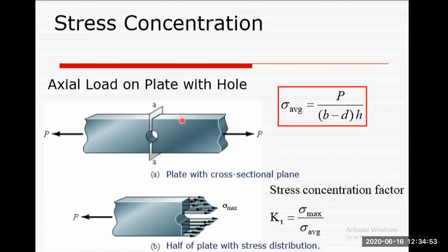Check out this example here. We have a bar with a hole, a plate with a hole, which is axially loaded. You're applying some force here, and at this cross section, the material will fail starting from this hole here.